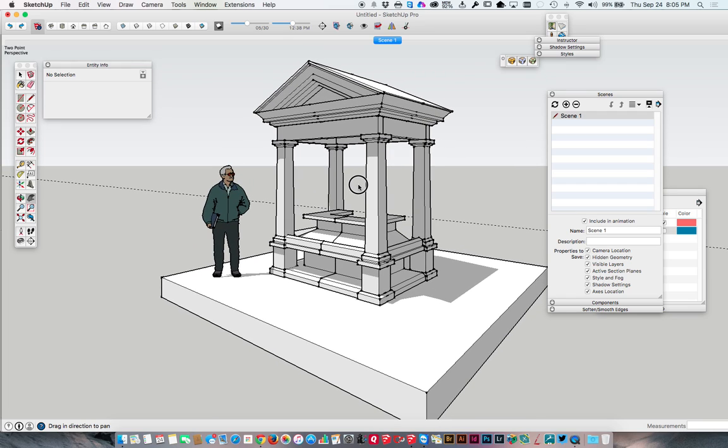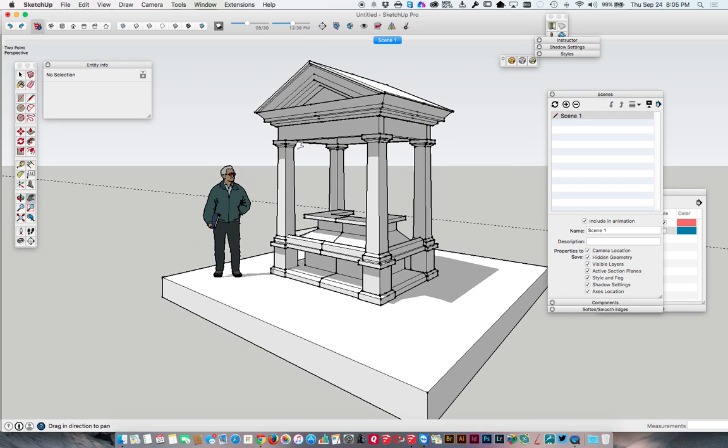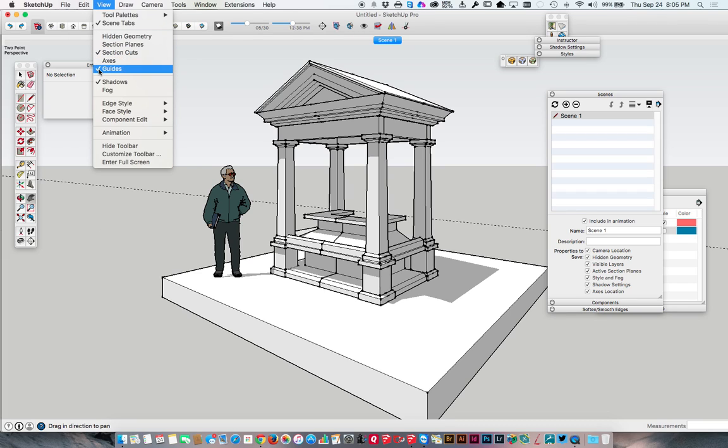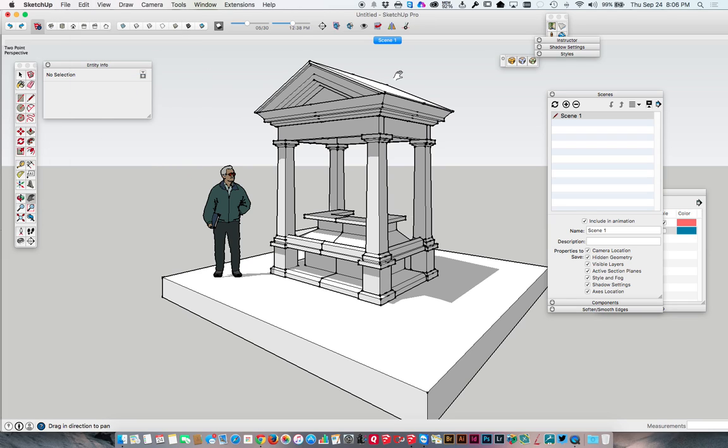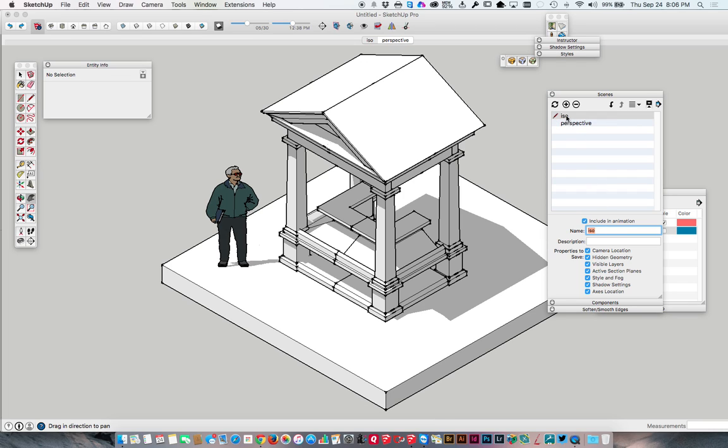Now I'm just positioning it somewhere on the screen to look good. So that looks good. Let's go ahead and get rid of our guides here. Let's delete the guides. Okay, so let's make another scene. Here we can just add plus, and now it's a scene. Let's go ahead and name these. This can be the perspective, and scene 1, if we go to that, is the ISO. Okay, and if we double click on these, we can go between them.